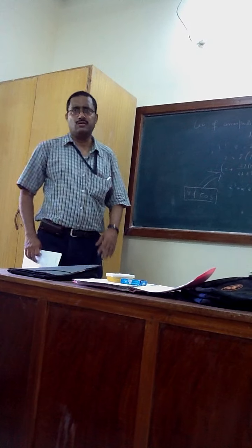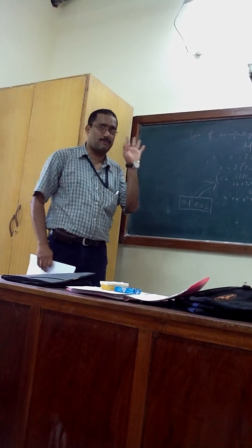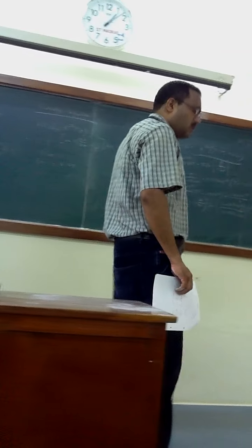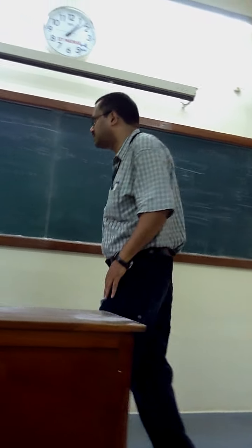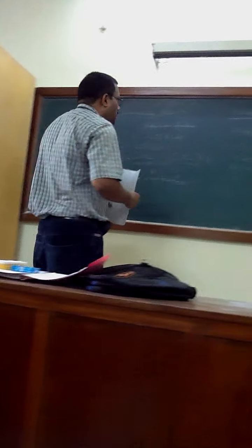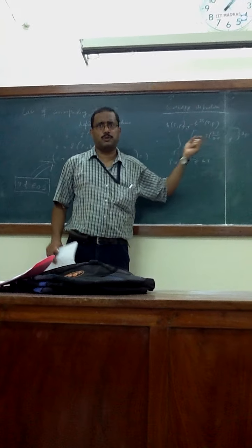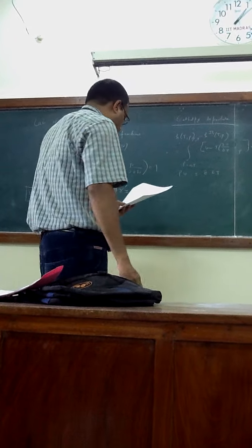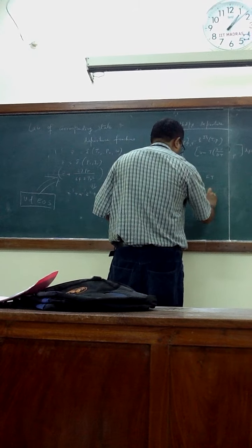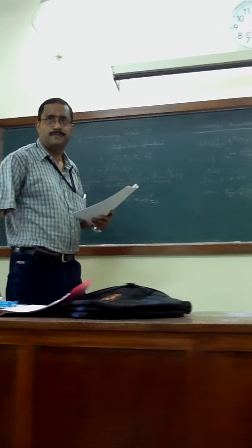We can actually do the Laplace derivation. I will not ask that. Maybe Rahul can give those calculations later on if we have time, but I am not asking. It may take another couple of weeks to get the entire set of compressibility factor results. So remember that this is the departure formula I will be using in terms of the corresponding state. So Pv equals Z R T, and from here one can calculate V as ZRT by P, and this Z is nothing but a function of PR, TR from your compressibility factor chart.